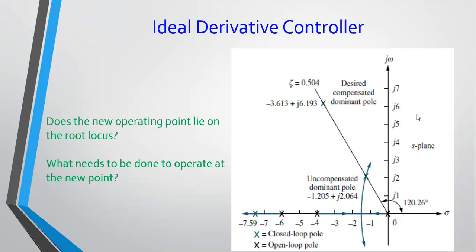Remember we said all points in the root locus would contribute an angle of plus or minus 180 degrees. So if you want to take this point here and link it to all your poles and zeros, in this case there's no zeros. So if you create vectors here from your finite poles to this point here, and you get all your angles which are created and you sum that, bearing in mind that your poles would have negative angles, this sum should come to plus or minus 180 degrees. So clearly this point here would produce an angle of plus or minus 180 degrees, but this point would not.